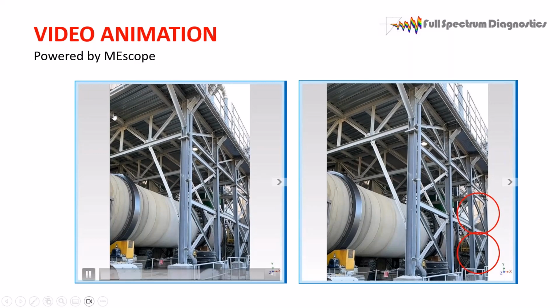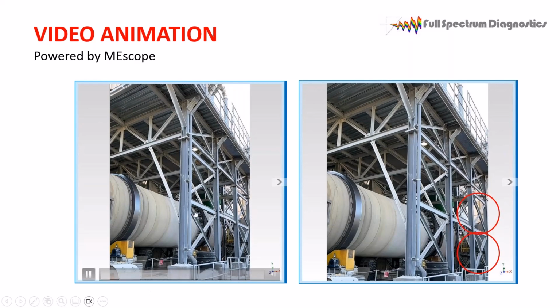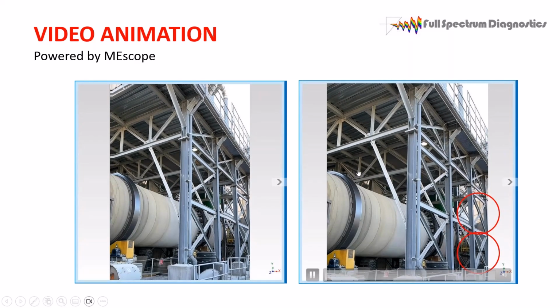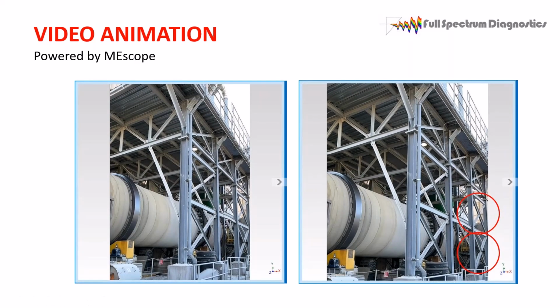We were doing the vibration analysis and we stood back and got these videos, and these aren't even the good ones yet. You'll see the good ones. So this is a time waveform. This is the discrete Fourier transform, and I put my cursor, I believe, on something around 900.